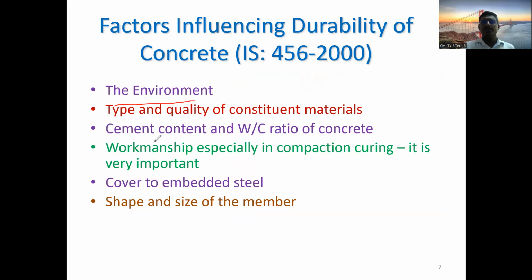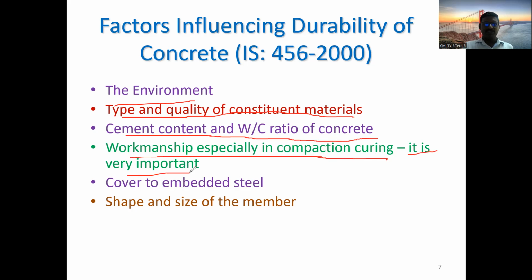So how does the environment affect the durability of concrete? Then types and quality of the constituent material, then cement content and water cement ratio of the concrete. Then workmanship, especially in the compaction and curing, it is very important. Then cover to embedded steel and shape and size of the member. So these many factors are affecting the durability of concrete.